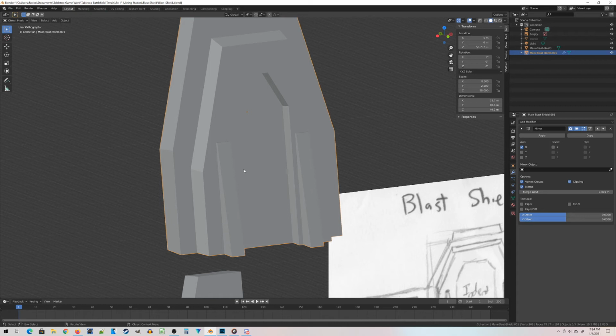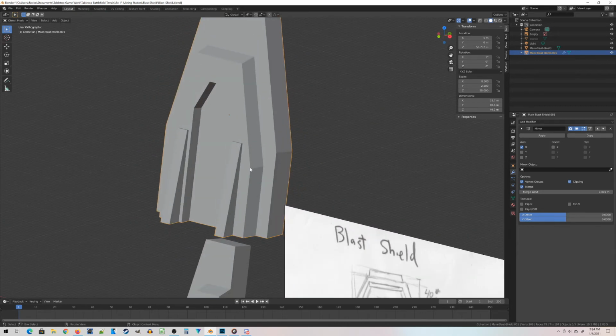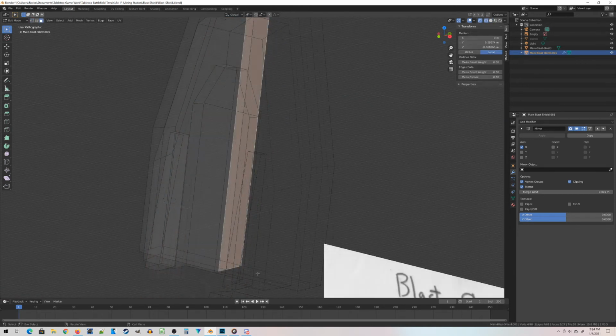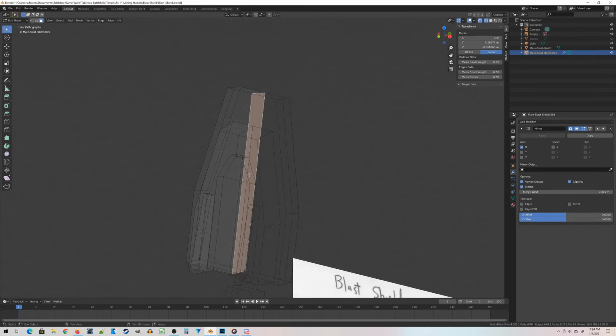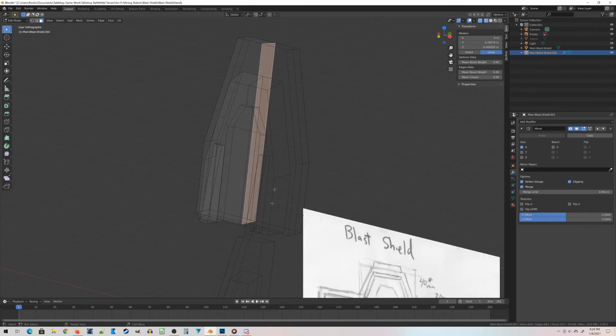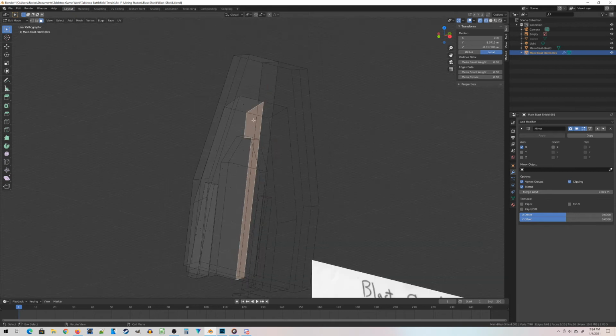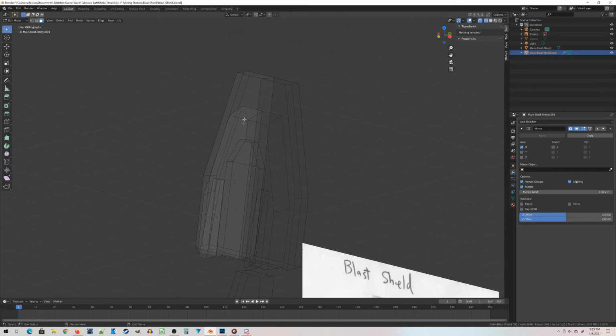But there are a few more things that we need to play around with before I can call this one solid object. So jump back into edit mode by pressing tab. And we're going to go to face select mode. There are internal faces here because what we had before was a solid object. This is a face running down the middle of the object. You want to delete that one, so press X and then choose faces. And then there's at least one more internal face here to delete. Now, we're deleting that because that can cause issues with some slicer programs. The rest of the stuff should be fine to leave.